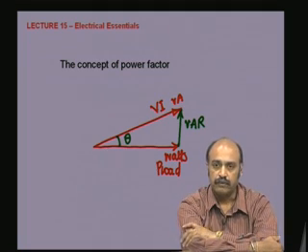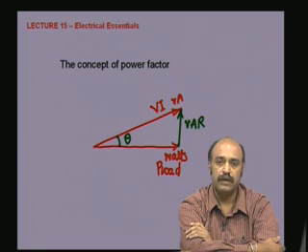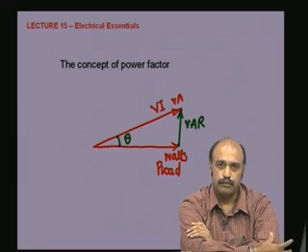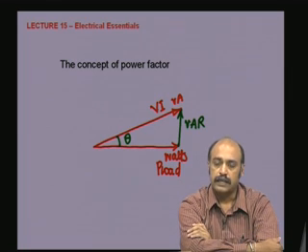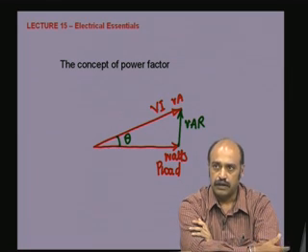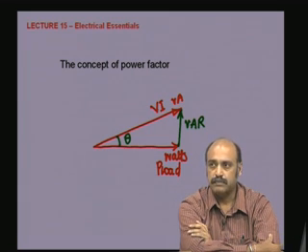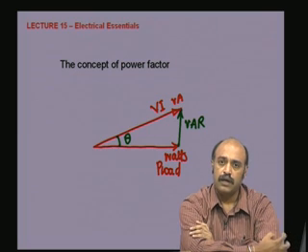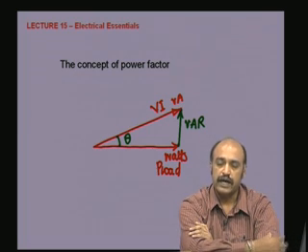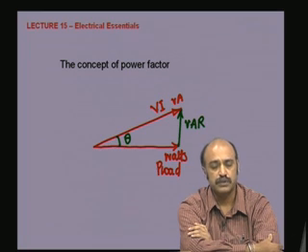Lecture 15 brings you the important concept of power factor. Power, when we draw from the source, has two components, the reactive power and the active power. The active power is the one which actually goes to the load; the reactive power goes to set up the storage mechanisms. As I said, the energy flows from the source to the destination. You will see that energy gets stored in a kinetic or electric potential form in between before it reaches the load.